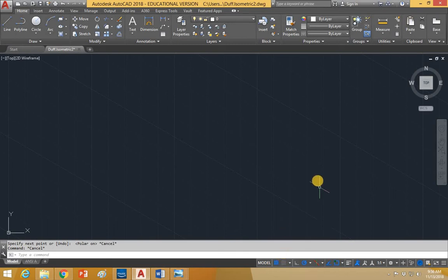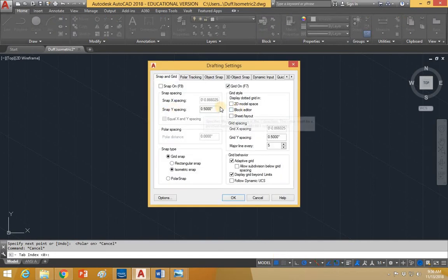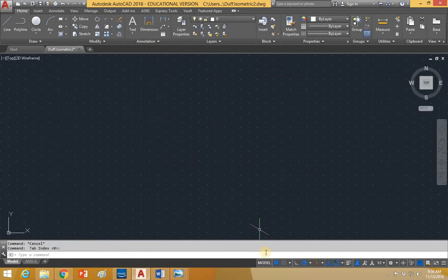The other thing we can do to make things a little bit easier is we're going to use quarter-inch increments. So right now we have the grid on, and I'm going to go to grid settings. My grid right now is set to 0.5, so I'm going to change that 0.5 to 0.25. Oh, that's my snap, sorry. I'm going to deal with snap in a minute, so leave that at 0.5. Put this to 0.25. That's my grid spacing, 0.25. Say OK, and then everything got closer together.